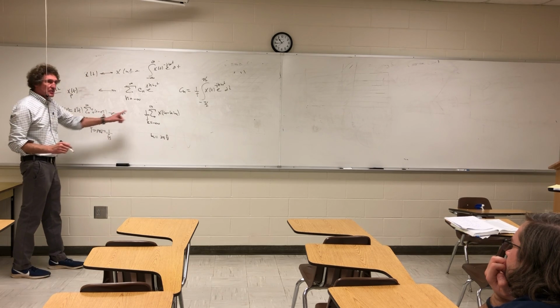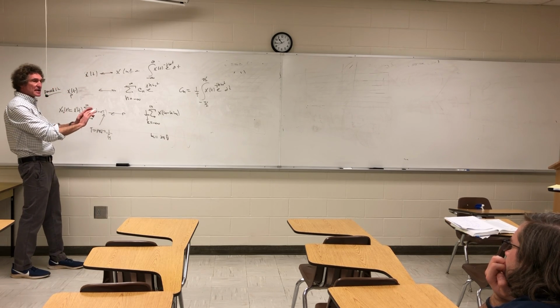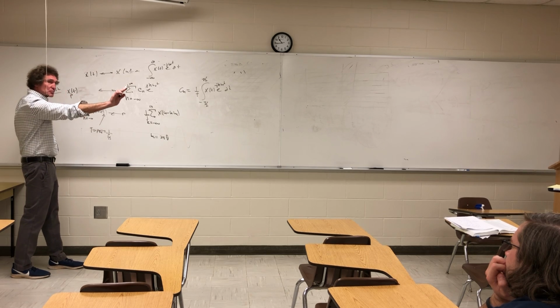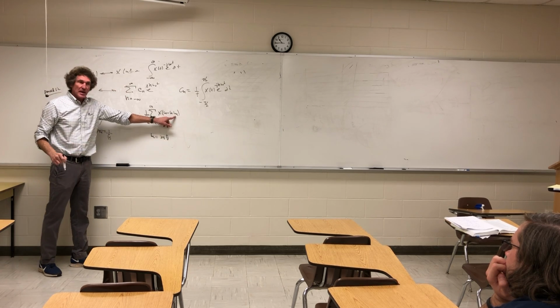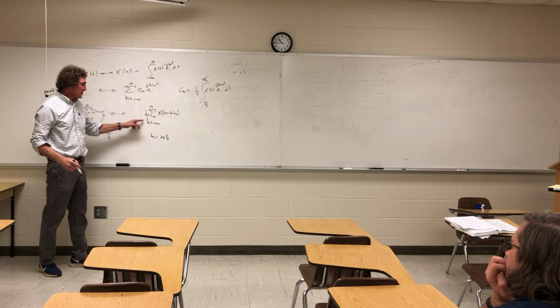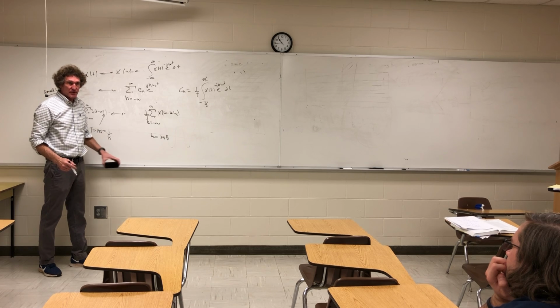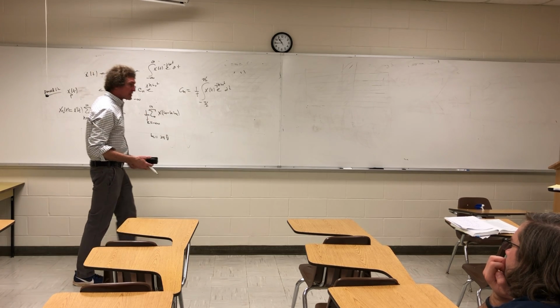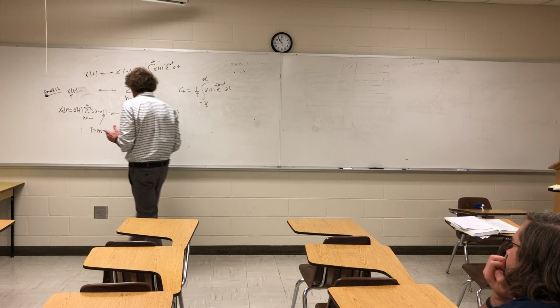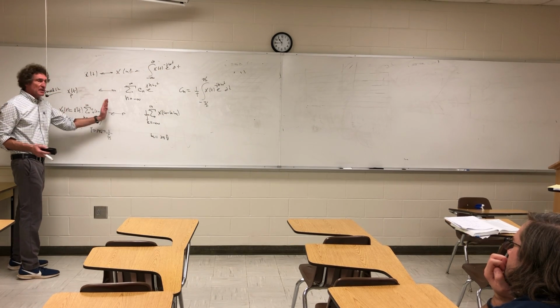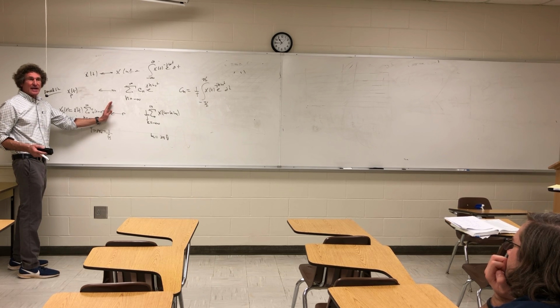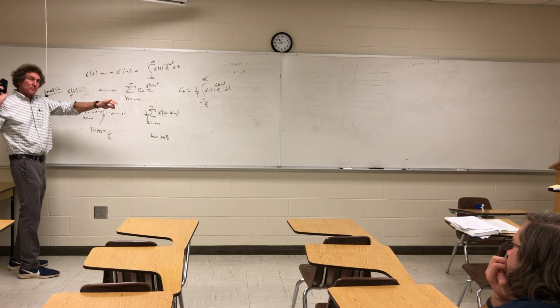Y'all remember doing this? The only thing I'm saying is when you sample a signal, it basically takes that signal's Fourier transform and it spreads it out over the band every omega S. Same thing, it scales it by 1 over T, right? Or multiplies it by the PRF, pulse repetition frequency. Those are things we've covered. This is all important. Then we did one other thing, I'm not going to do it right here, but we took this and we multiplied it by a simple pulse function of width dwell time, right? So now we had an actual continuous time series of a radar dwell time, right? With all those PRIs, correct, class?